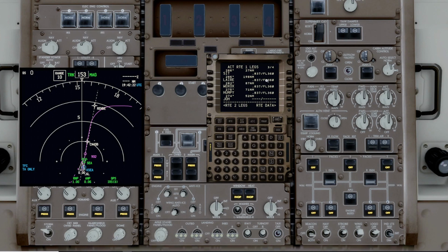And then we can go to our flight plan and put in the rest of these if we choose to, at least up to the point where we're going to start our descent. And then, of course, on the VNAV page, we have our forecast winds for the descent. They were put in automatically, so this has an effect on the top of descent point. It'll move the top of descent point back or forward based on these descent forecast winds. So we certainly have enough to get started on winds up to ANN, and then we go in the flight plan and get the rest.